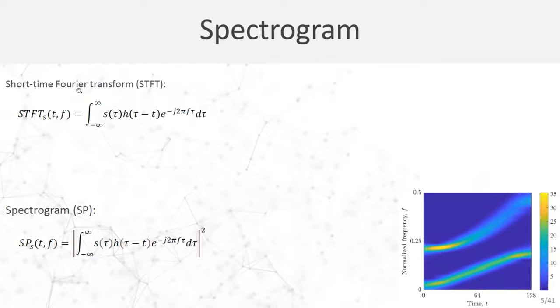First of all, we defined the short-time Fourier transform that provides us the time-dependent frequency spectrum of the signal by calculating the local frequency spectrum on the sliding window. The spectrogram is the first used time-frequency representation, which was obtained as a quadratic model of the STFT.